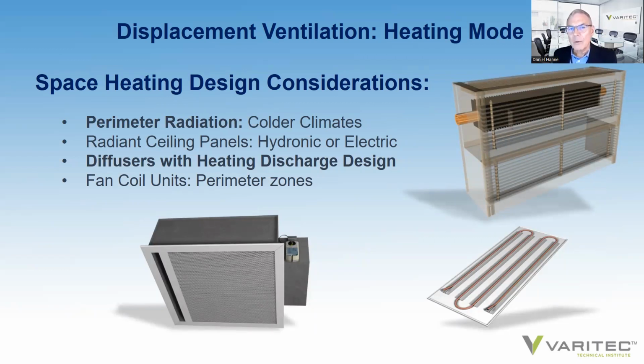I've had very good results using ceiling displacement ventilation for the Banner Health Clinics and for the Banner Boswell 26 patient room renovation project here in Phoenix, Arizona. What it is, it's a 2-tiered plenum sheet metal box that sits on the top of a diffuser with a large area perforated plate for displacement ventilation in cooling mode. And then in heating mode, there's a 2-position damper that modulates to close the air serving the cool air diffuser plate and injects the warm air into the linear diffuser where there's very little face area. So you achieve high discharge velocity, allowing this device to wash perimeter walls and windows in heating mode.